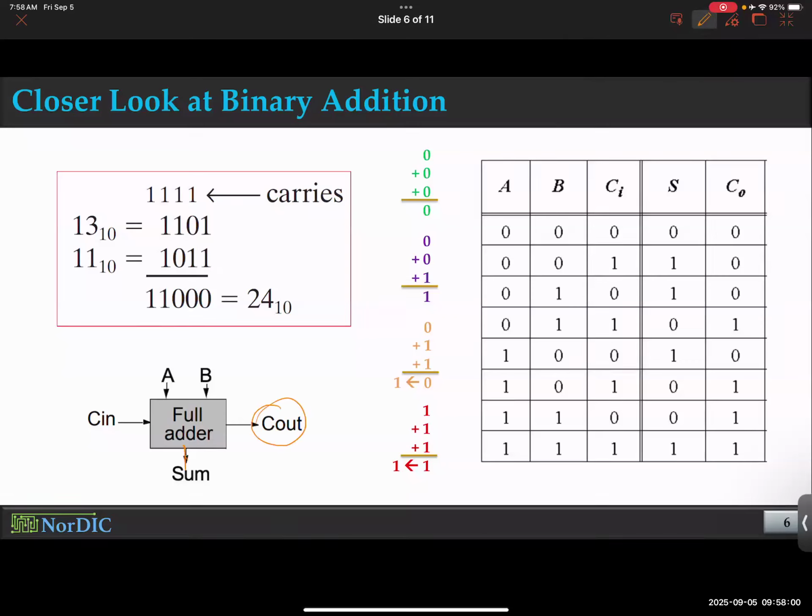This is a unique Boolean logic that you're seeing. Typically, you're used to looking at multiple inputs, one output, right? Here, you're looking at multiple inputs, multiple outputs, at least two outputs, sum and carry. It's interesting, but not too crazy, I think. Okay, so when we create the truth table, you have combinations of inputs and then you have combinations of sum and carry, which both of them are output. You have output 1 and output 2. So I have to come up with two Boolean expressions, one representing sum, one representing carry.